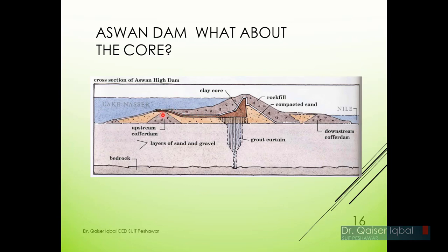There is another problem in earth-filled dams, because water can pass through the earth, through the soil, very easily. So which will basically result in piping and erosion downstream. We will discuss all those phenomena in the later topics. So to cut this water path, so it should not go down this route in a very large quantity, we use clay, which is once again an application of geotechnical engineering, because we know in geotechnical engineering that clay has less permeability, so it does not allow the water to pass through its pores.